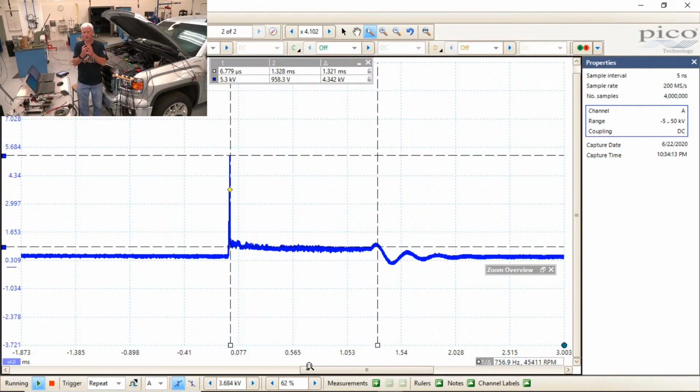The ones that are really well shielded and have igniters built into them, they don't tend to work very well on. And in those cases, some people will pull the coil out and put a little jumper wire in between it to clip onto it. With this vehicle here, other than amperage, I cannot see the primary side of the coil. I can check the primary. If I want, I can go through and check some of that right now.